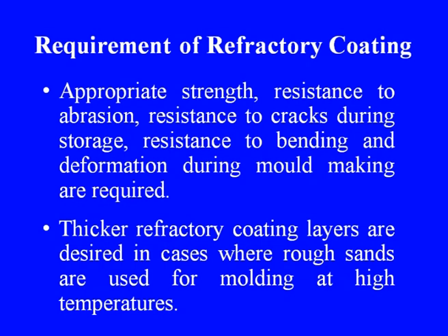Appropriate strength, resistance to abrasion, resistance to cracks during storage, resistance to bending and deformation during mold making are required. Thicker refractory coating layers are desired in cases where rough sands are used for molding at high temperatures.